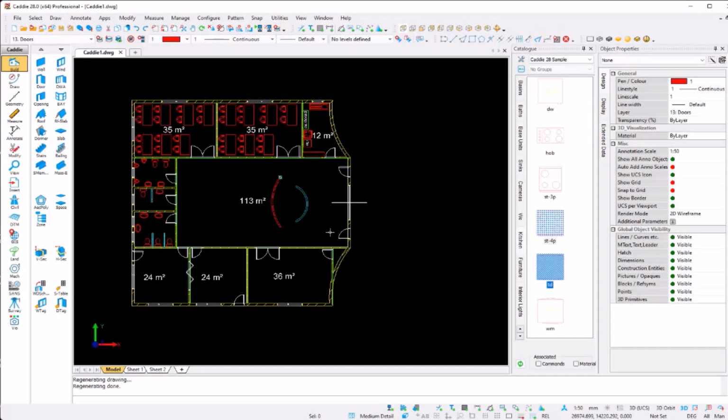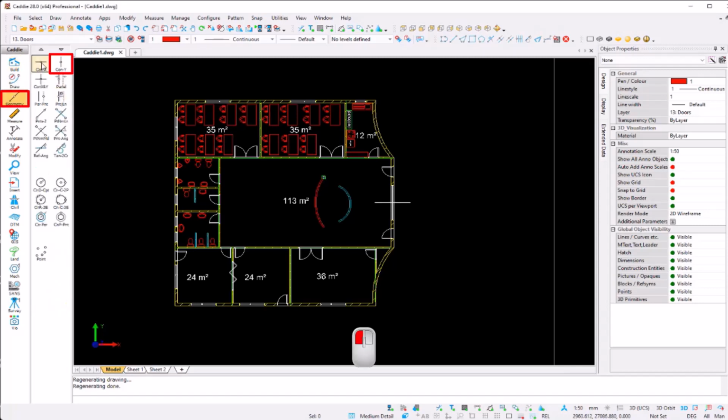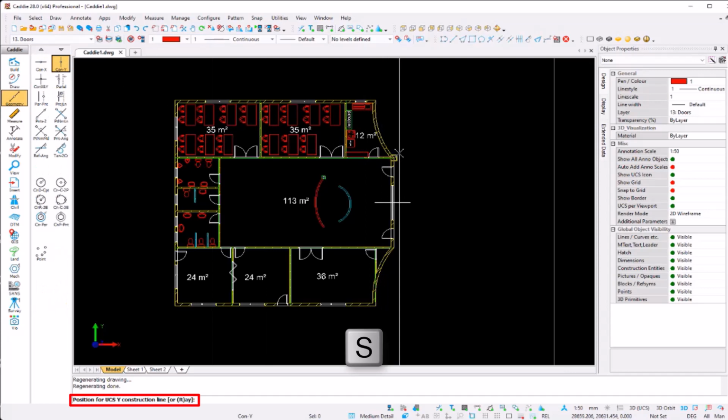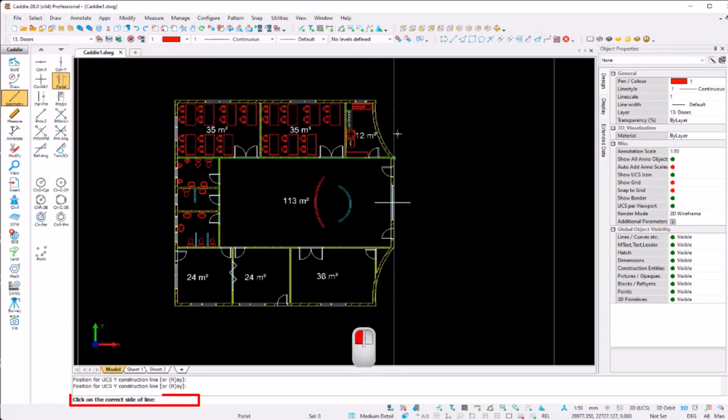Now the next is going to be your roof. Now when it comes to the specification of the roof, it needs to be a Dutch gable design with gutters and downpipes, as well as it needs to cover a drive-through that is wide enough to accommodate 2 motor vehicles side by side for dropping off and collecting of delegates. You can decide 6 meter or 7 meters. So let's go geometry. I'm going to say snap, parallel, 7 meters, that's fine. So that will be the size for my drive-through.